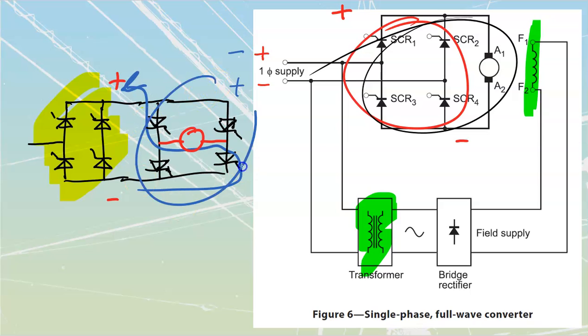This is referred to as an H bridge that we would have off of here, where it's just driving current through in the opposite direction. This yellow one here is going to control the amplitude. This other H bridge over here just controls the direction. That makes this a really, really useful component, because now your DC motor can be solid state driven into forward and into reverse at any sort of varying speed.